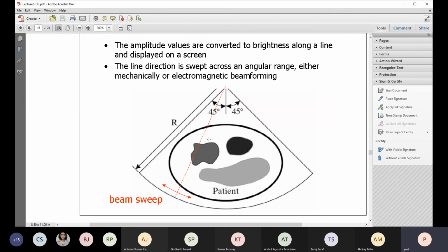The imaging is usually done digitally by steering the beam at a certain angle and then monitoring the corresponding echoes. Then the depth-time profile is converted to a depth profile, and we have the intensities available in polar coordinates, rho theta coordinates.